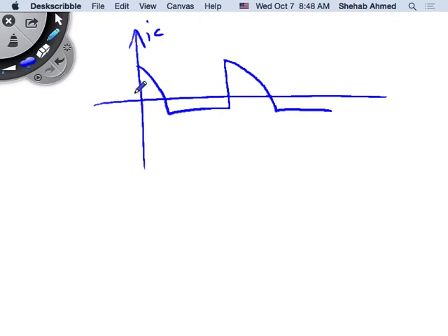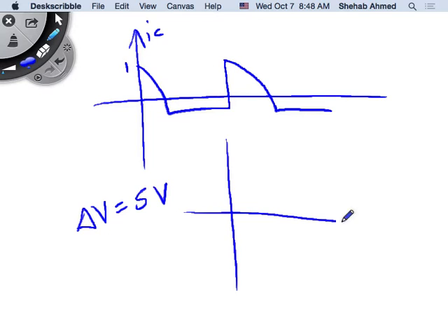If I give you this IC waveform, and I tell you I would like this capacitor to maintain ripple within, I don't know, 5 volts. So in some circuit, what is the value of capacitance that would do that? And I give you all these values. Let's say this is 1 amp, and this is a difficult waveform, but let's say I give you something that looks easier, okay?